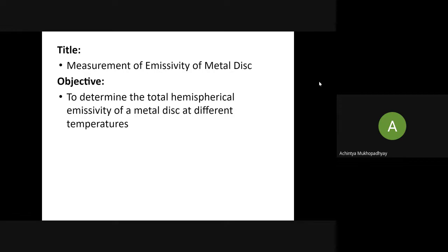So if it is directional spectral emissivity, then we generally write it as epsilon prime with a subscript lambda, and the functional parameters are lambda, theta, phi, and of course temperature T. When we make it directional total, the prime remains, but the subscript of lambda goes, and from the list of parameters also the wavelength lambda drops out, so it is a function of theta, phi, and T.